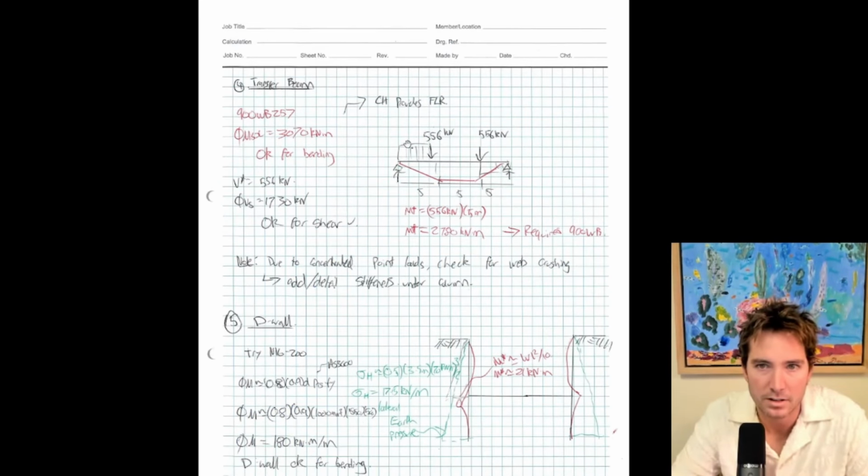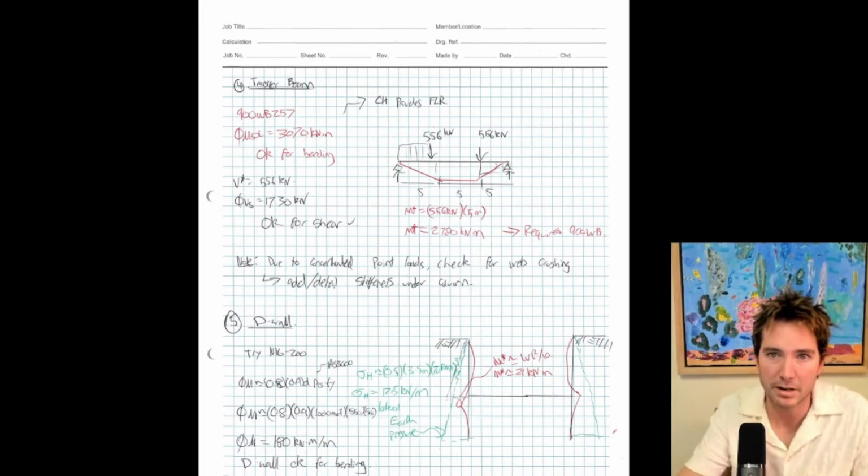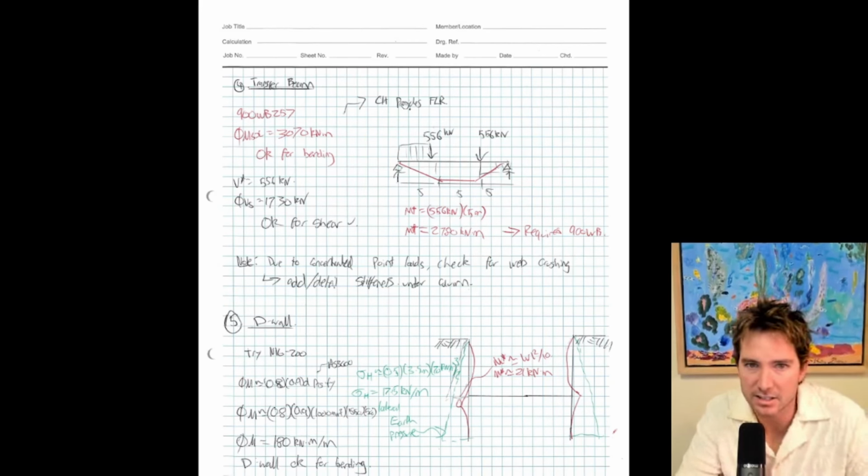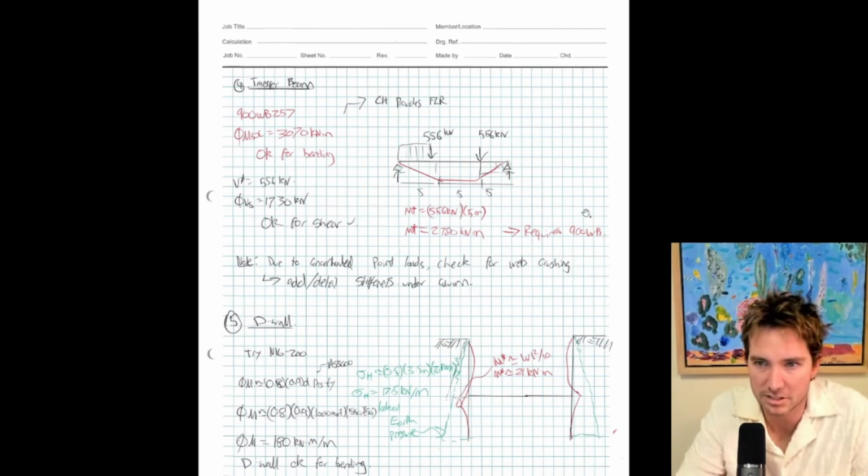Transfer beam, again, as I just mentioned, I picked that up from my load column rundown table on the previous slide. Then I'm just briefly drawing some, like a basic bending moment diagram for my transfer, shear force diagram, do some calcs. I think I started like, in my concept design I had a 700 WB. You can see here, similar, I obviously might need to check some of my rule of thumbs, but I've upsized the transfer member because I need a 900 WB for bending.